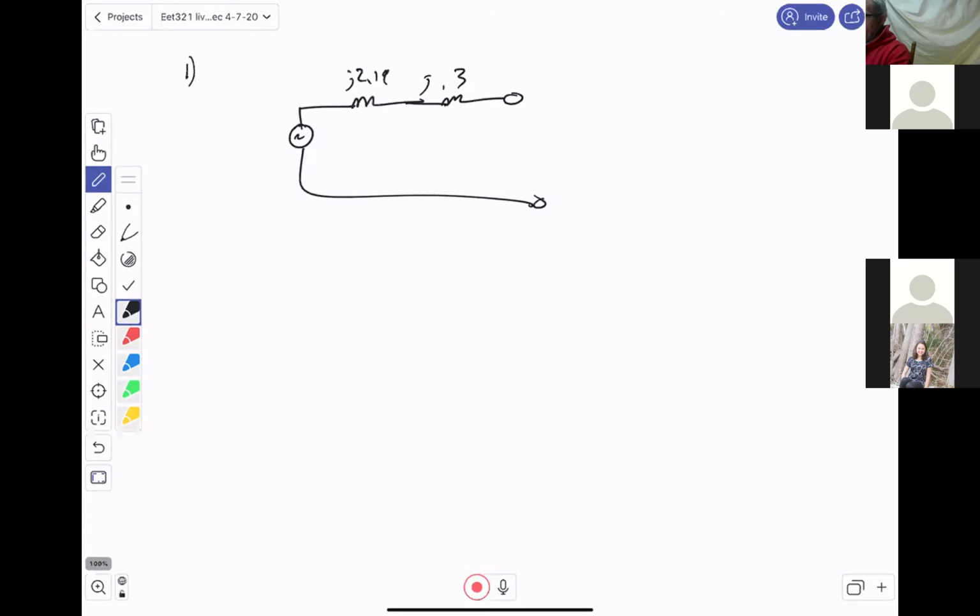But essentially what you have is a voltage here, whoops, wrong side, of 13.2 kV at an angle of 0, right? That's the nominal voltage because this is the terminal. This is what you actually have access to. This EA is based on whatever value it needs to be. So it'll give you that specific value to go ahead and drive that. So now it says it's delivering full load current at rated voltage and a 0.8 power factor.